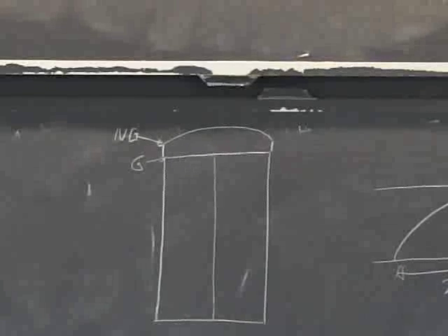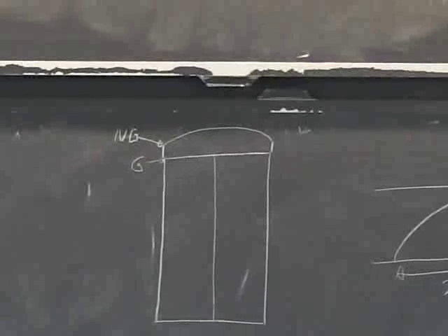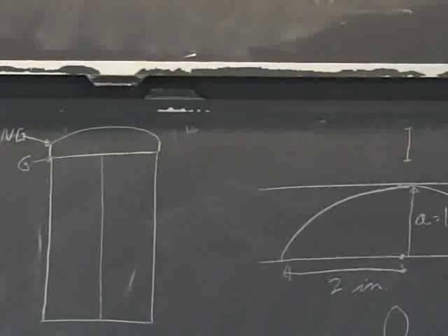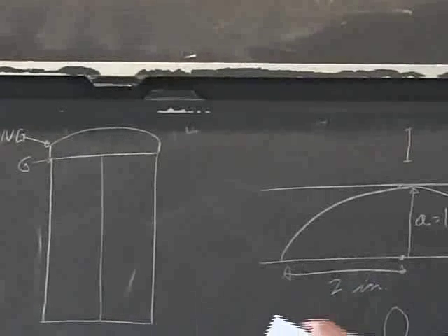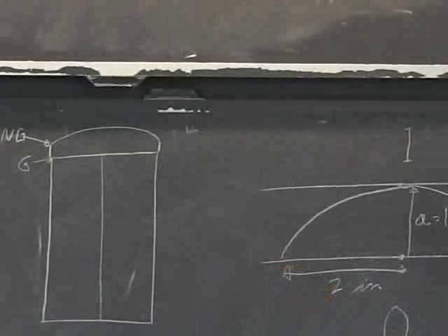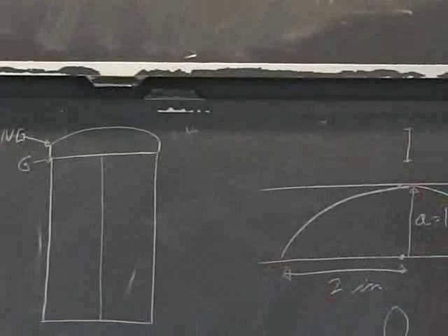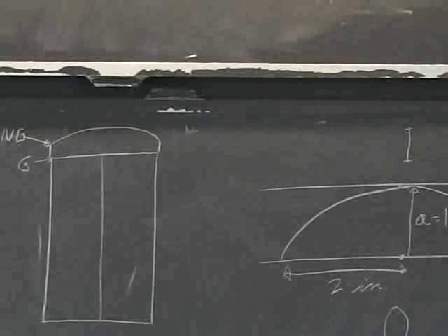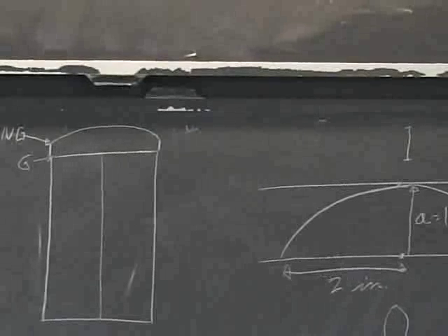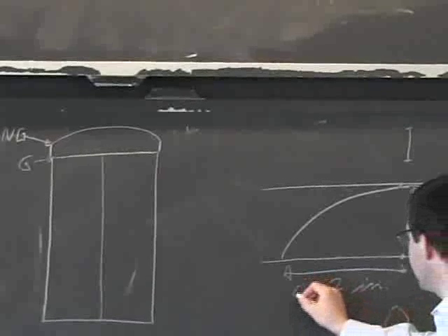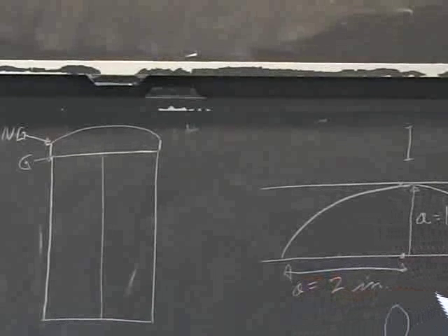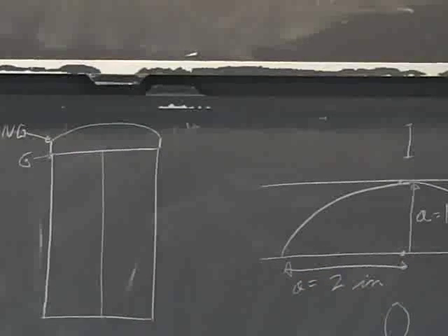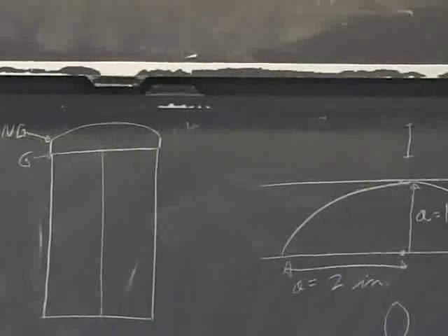The solution will vary a little bit depending on how you estimate the crack geometry, but not a whole lot. So I'm using this as an example, but it essentially means I'll have 4 inches of visible crack on the outside before I start seeing the crack on the inside. It's not unreasonable. Now, just from this information here with A and C, when I calculated, I got this factor of 1.28 that I plugged into the Q.